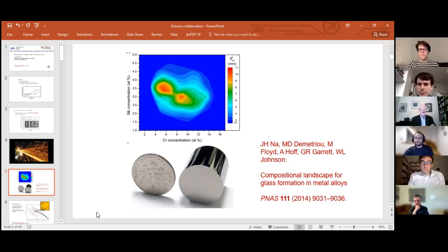No, you would find, in say the geometry that we have there, this is achieved by pouring the liquid into a cold copper mold, and obviously the material in direct contact with the mold, which is the periphery of the cylinder, is cooled rather fast, and the cooling rate decreases steadily towards the central axis.